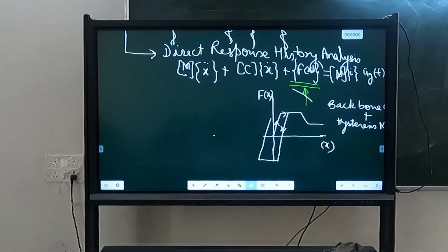So you can do a test of every member of a building. Again, a very cumbersome thing. We do tests on similar types of members. Either those tests have been done in the past by somebody else, we can take those results, we need not repeat it because it is a costly thing. Those components whose behavior is not known to us, those we can test ourselves. Suppose I am using a new type of column, a completely filled column in place of our normal one.